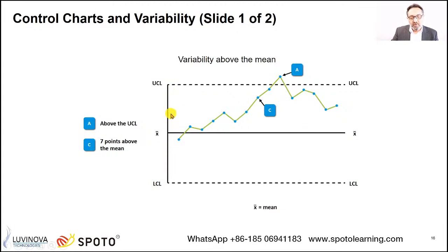So first of all, we agree on a range, which is your acceptance criteria. Based on this range, you have the mean now. From the mean, you decide on something called the upper control limit and the lower control limit. And then you start taking readings from your outputs, which are deliverables. It might be a dimension, it might be weight for the deliverables, any attributes about your deliverables. This is based on the acceptance criteria.